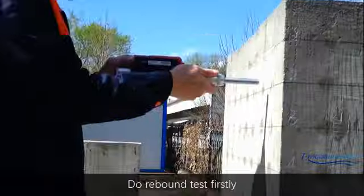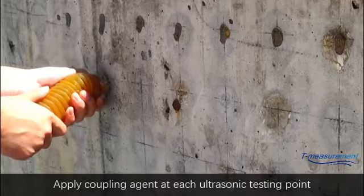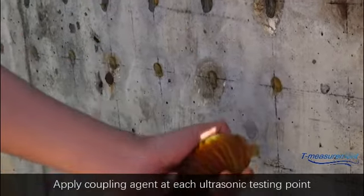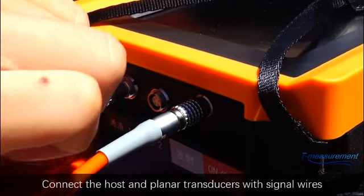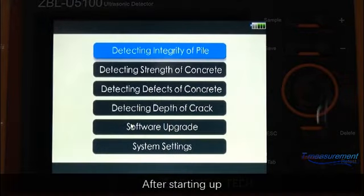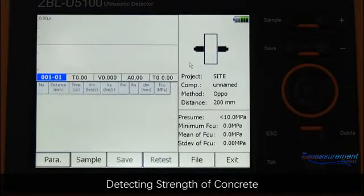On-site test. Do the rebound test first. Apply coupling agent at each ultrasonic testing point after the rebound test. Connect the host and planar transducers with signal wires. After starting up, enter the detecting strength of concrete.